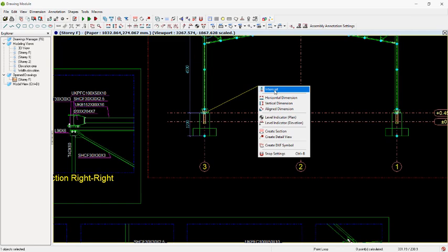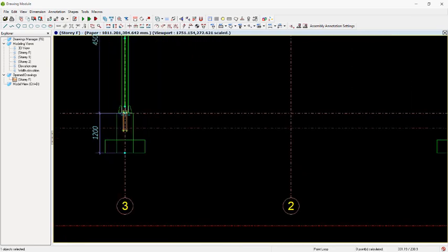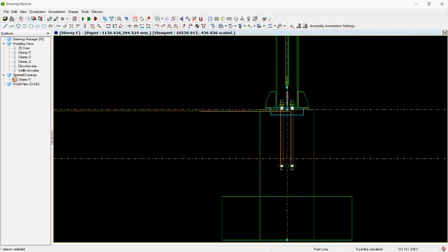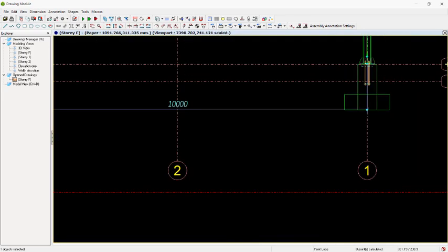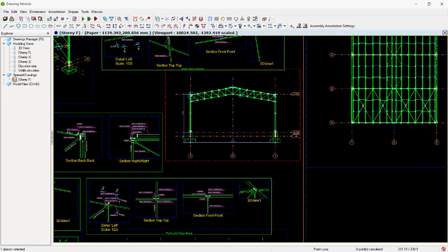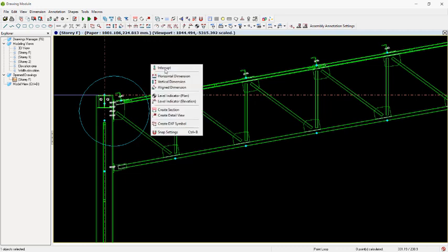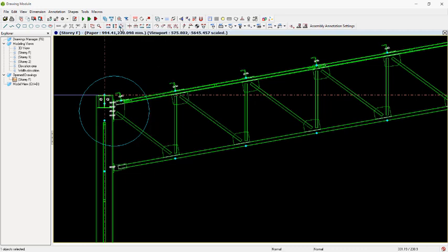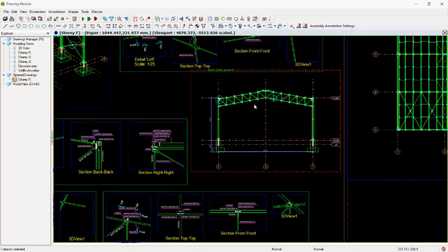Okay, so whichever dimension you want to do from this point. This is horizontal, so you interrupt, and you have to pick the horizontal dimension too. Pick that point, come all the way to this point, pick that. So you right click right there to have 10 meters spanned in that direction. Also, if you want to make an angular dimension, you can use this for angular dimensioning successfully. So this is how all of this is used.